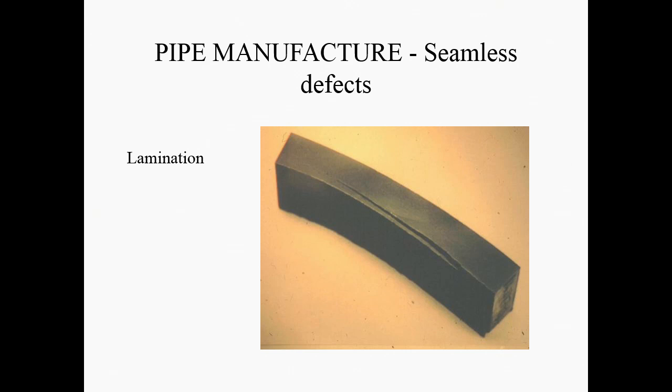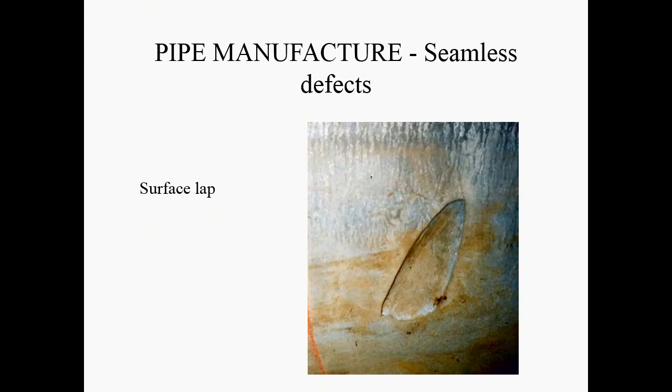And the pipe, when the crack runs through it, it will find the path of least resistance, so it will tend to jump from one inclusion to another because that's a slightly lower energy process. But this is a ductile crack, really. It isn't associated with the defects. It starts from the surface and it just runs in quite some distance. Now that's obvious. If you see that, you know that you've got a bad pipe and you just reject it. It was very straightforward to see.